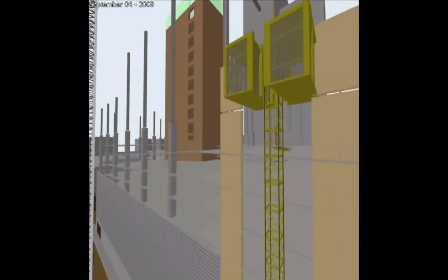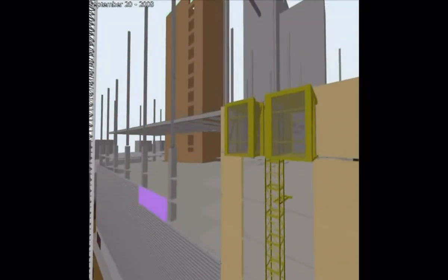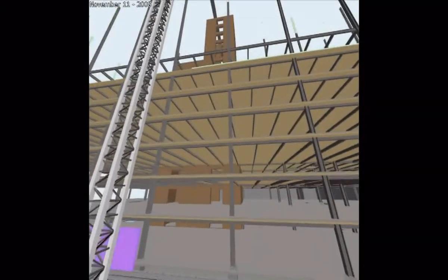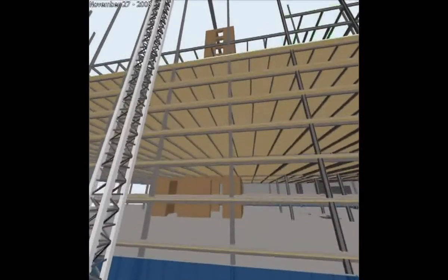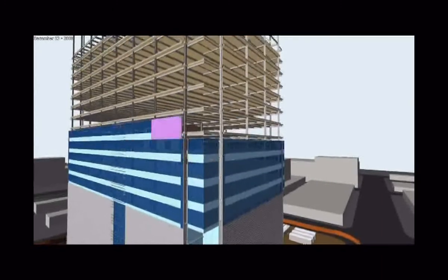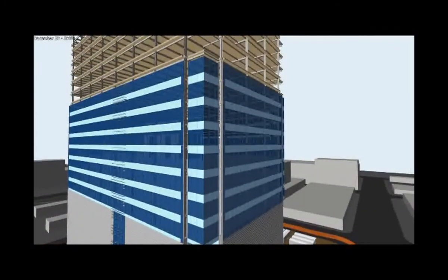And then during the project cycle, you can do what we call 3-week look-aheads, where you're taking a look out for the next 3 weeks, bringing that information to the project teams and saying, look, this is a snapshot of the next 3 weeks. Sub A, this is where you're going to be working. Sub B, this is where you're going to be working. We don't want you guys to overlap. So you just basically focus on the different areas you're going to be working in.